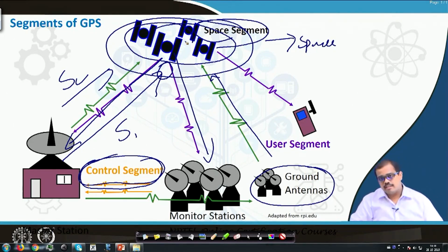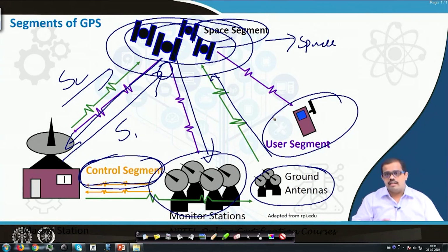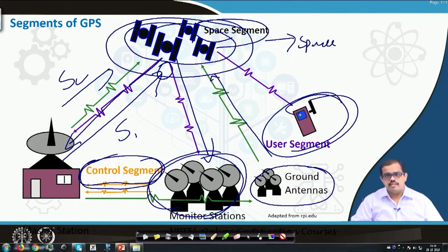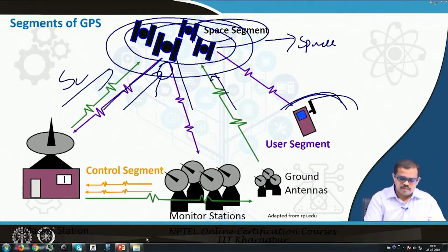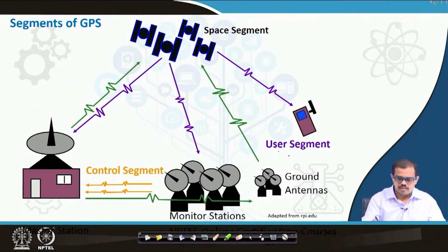Once the corrected signal is sent back to the satellites, any number of users can use it, and it is disseminated onto the Earth's surface, where there are certain distortions due to the ionosphere, etc. Based on this, there is a certain loss, and the signal that is not lost reaches the Earth's surface, where it can be used by monitoring stations and in the user segment. So, this is how the entire segments of the GPS work. Let us understand each and every segment of a GPS in a better way.